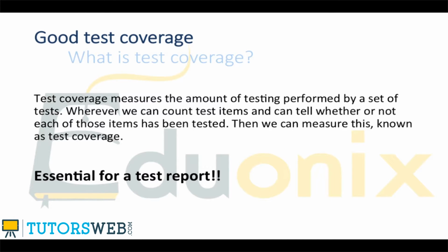How do you ensure that the test meets the test quality and coverage needs of the design, especially in common situations where the board designer and the test developer are from two different companies or even two different sites? Well, test coverage measures the amount of testing performed by a set of tests. Wherever we can count test items and can tell whether or not each of these items has been tested, then we can measure coverage. This is known as test coverage, which is essential for a test report.